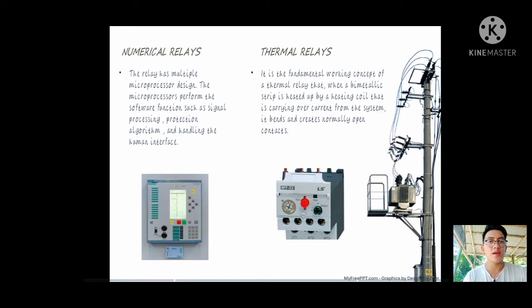Next is the numerical relays. In numerical relays, the relay has multiple microprocessor design. The microprocessors perform the software functions such as signal processing, protection algorithm, and handling the human interface. Si numerical relays is naka-design siya sa microprocessor which nagpe-perform ng software functions sa signal processing, protection algorithm, and other human interface.